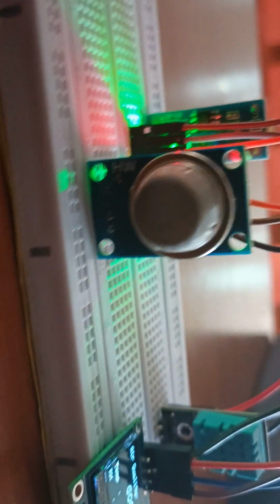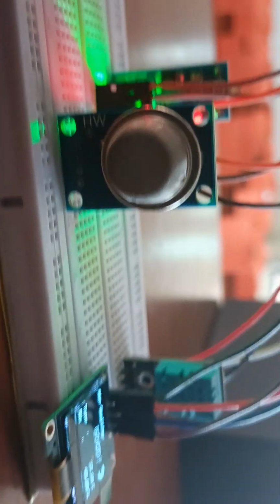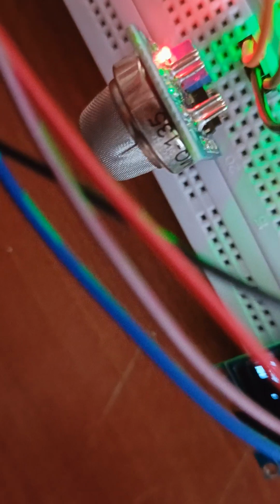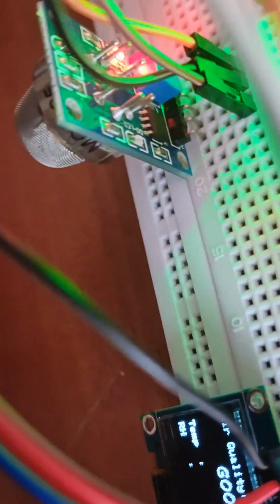Now we will talk about the MQ135 air quality sensor. This is a sensor that will detect the air quality, and to do this it will measure the concentration of multiple gases such as NH3, NOx, alcohol, CO2, carbon monoxide, and etc. The output is an analog output which varies based on the detected gases. The accuracy and range also vary depending on the gas being detected, and it typically operates around 5 volts.